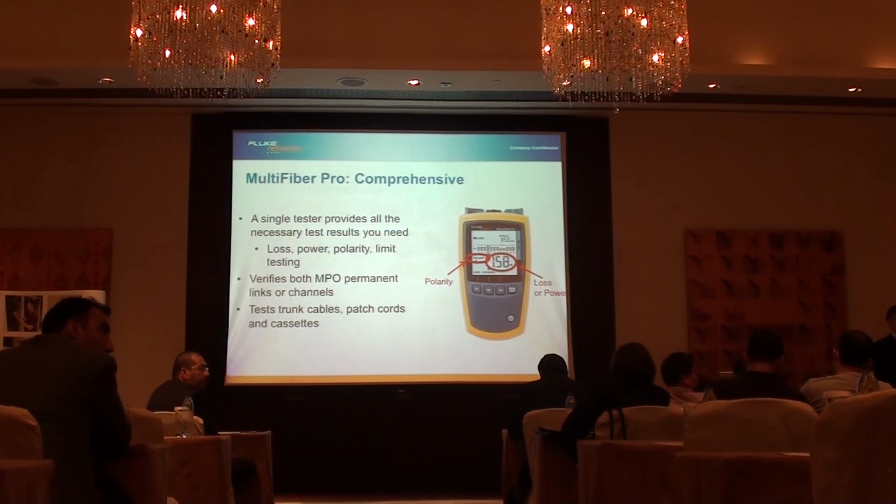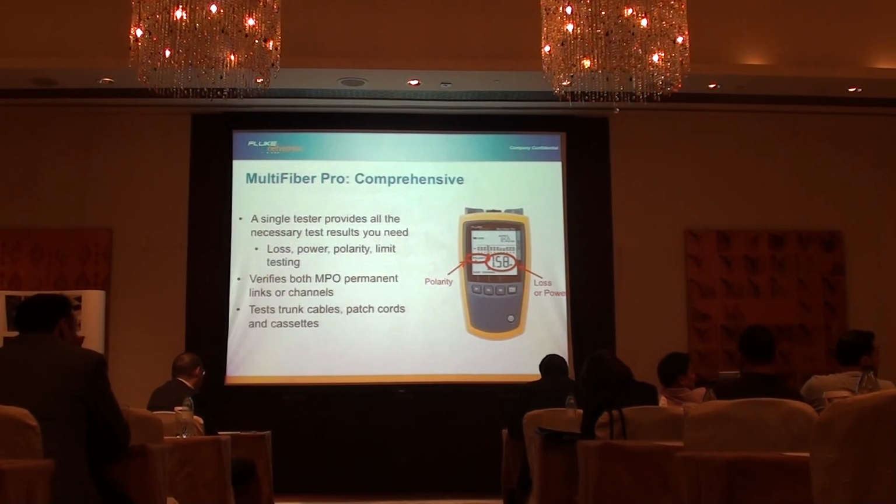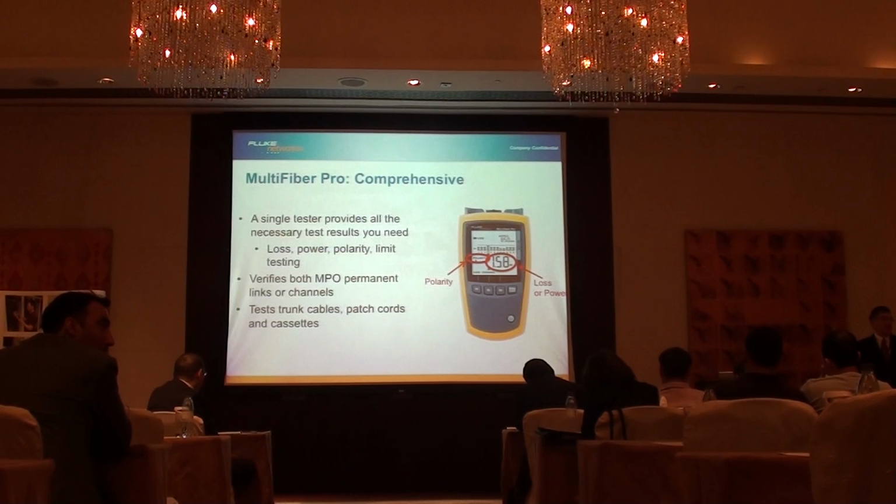So first problem isolation is how fast can you detect if the cable is good or bad. And this is how within 20 seconds you could do it, rather than 6-7 minutes that you have to do it individually, core by core analysis. And this is the value. What you need now is figuring out if this is okay or not okay.